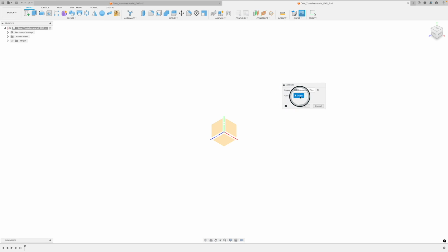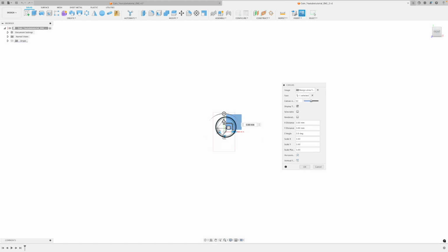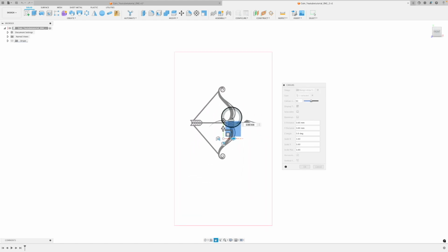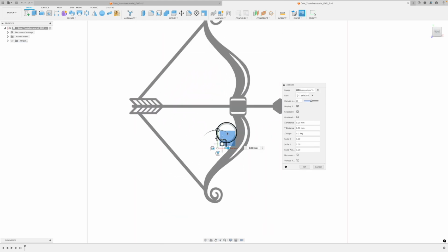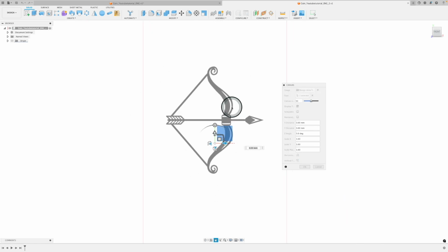So it tells you, okay, find the face, then select the face. It really doesn't matter which one it is. I usually use the front view. So if you go to your cube up here and click on front, then you can select the face, left click, and you can instantly see that your image will appear here on the plane, X and Y.